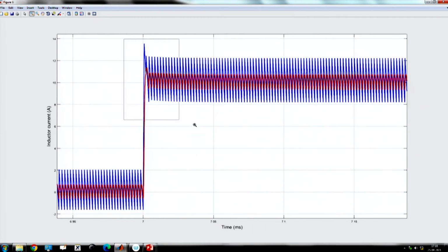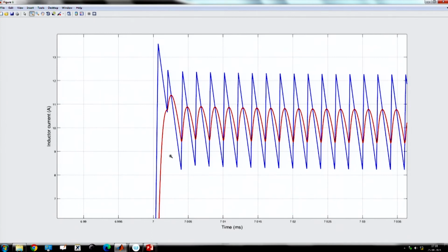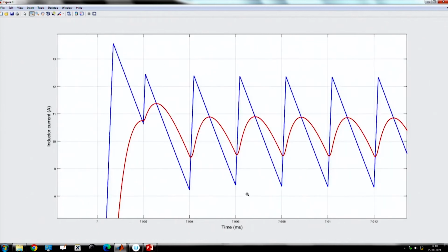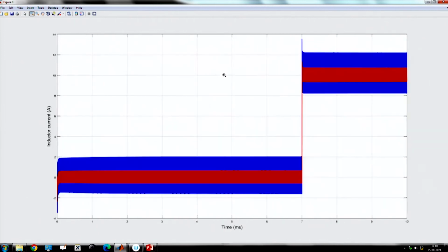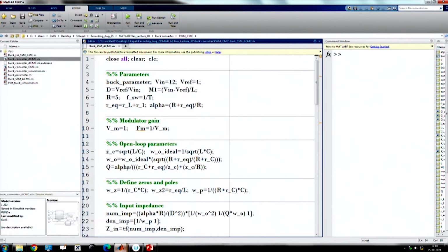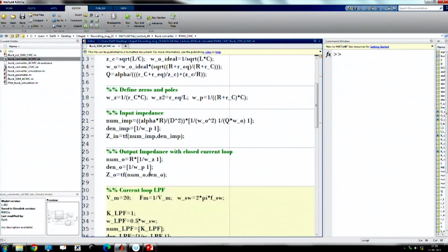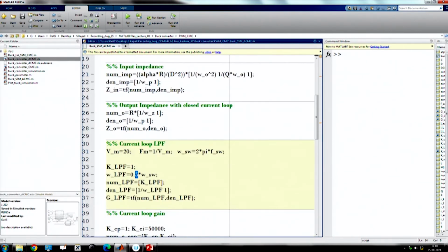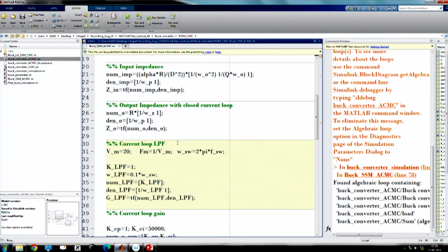So, it is important that the average current is maintained or not. It is maintained except for this slow overshoot, it is more or less maintained. Now, I want to slow down the current loop, that means I take 1/10 and check the current loop. I have not made any other changes in the current loop, and we will see whether it is going to respond or not.